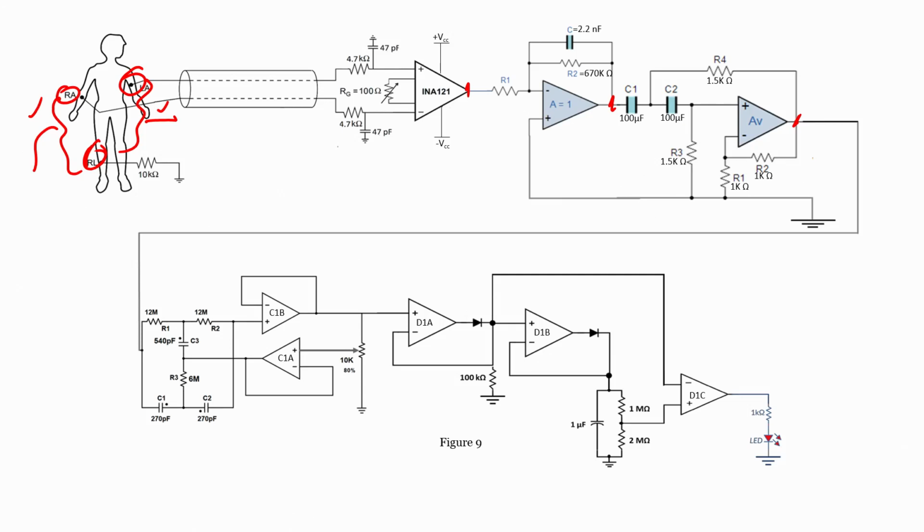But a differential amplifier cannot be used in this application, because the output that we get from the subject will be all common mode signal, and we require a higher CMRR value. A differential amplifier will always suffer from CMRR issues, and the input impedance of our instrumentation amplifier is higher compared to the differential amplifier. That is the reason we will be going with an instrumentation amplifier.